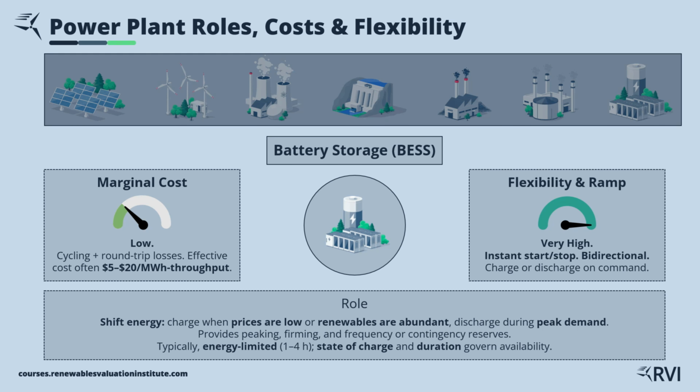Flexibility is off the charts. Batteries start and stop instantly, ramp in milliseconds, and can charge or discharge on command. That makes them perfect for fast frequency response, contingency reserves, and voltage support.